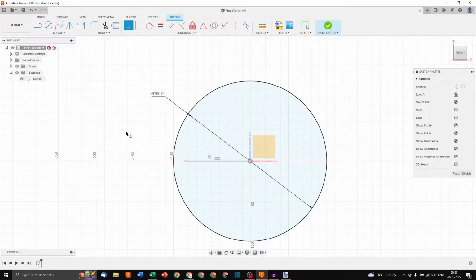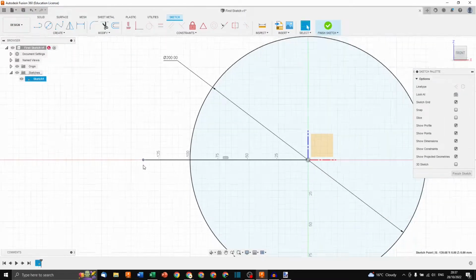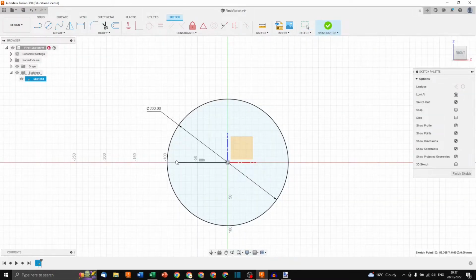I click on horizontal, and I'll now click on the line, and boom, it now snaps to horizontal, and it becomes black. Escape again, but it's not fully constrained, even though it's black, because there's this white point. I can therefore pull it more or less long. You can see the point is actually blue here, because it's not fully constrained.